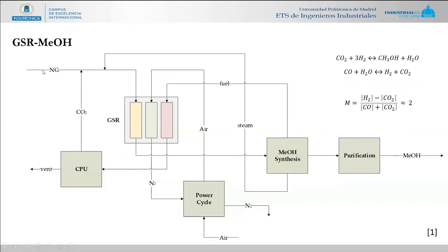So we have our natural gas inlet, which is mixed with steam and CO2. CO2 allows us to reach this module, because otherwise the steam reforming produces 3 hydrogens per molecule of CO. And then we have our feed to the synthesis. The synthesis loop requires a purge to avoid accumulation of inerts, and that purge precisely is then fed as fuel to the reduction step.